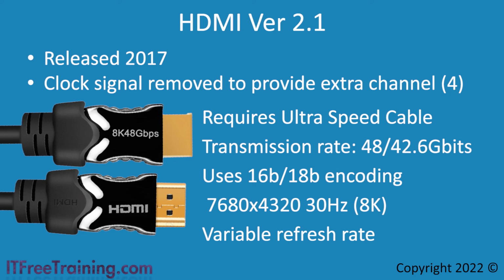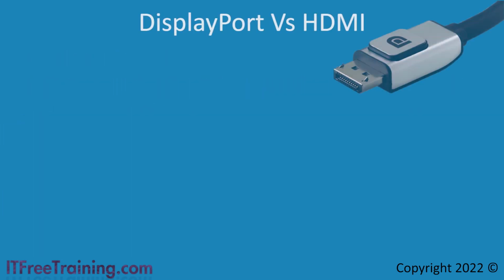This covers it for HDMI, but before finishing this video, I will quickly compare it to DisplayPort to give you an idea of what the main differences between the two are. There are a number of different versions of DisplayPort, which I won't go through, as I will leave that for the DisplayPort video. If you have a similar version of HDMI and DisplayPort, all things considered equal, about 90% of the features for each are the same. There are some things which are different, and this may affect which one you choose.